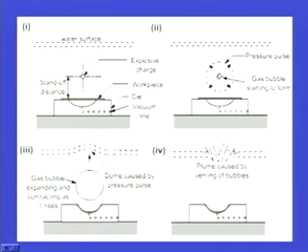Another important point to note here is that this is the water surface. As we have already discussed, the die and the sheet metal are immersed in a tank of water. So, this whole assembly that we are seeing here is under the water surface, this is being done under the water. So, we come on to the second, the detonation has taken place, and this is the pressure pulse that has been generated. After the pressure pulse has been generated, it goes and impinges against the sheet metal.